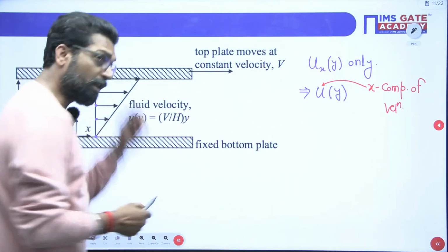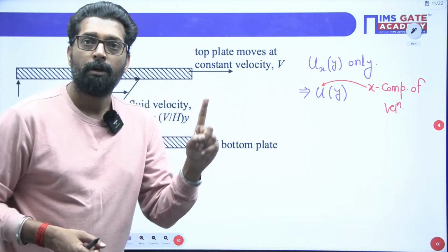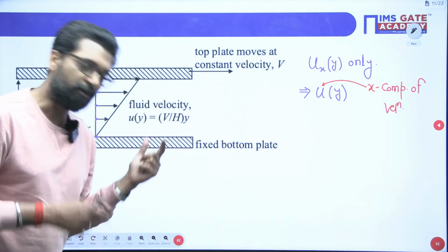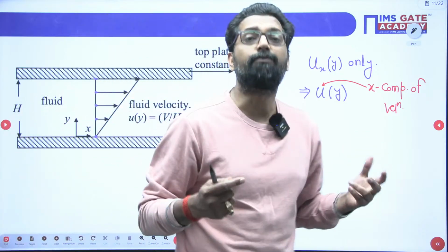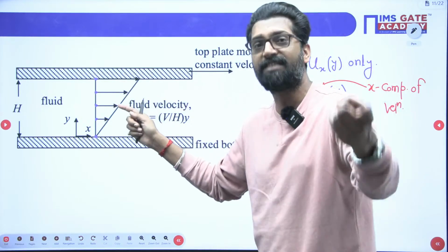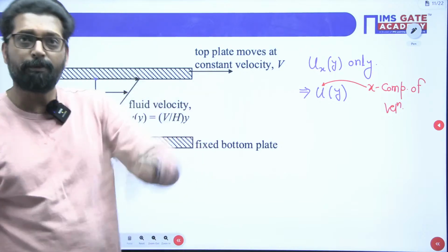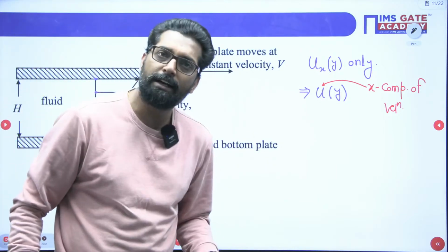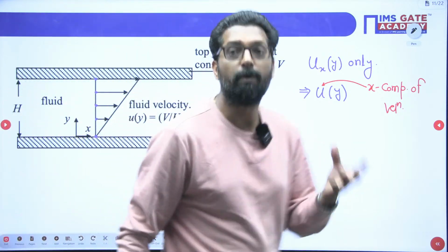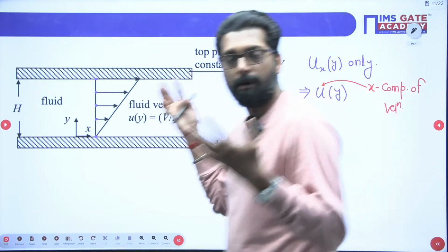Now, what is the profile then? Why do we bother about that? Because we have to find the shear stress within the plate. From the shear stress, you can easily find the viscous stress. Due to that viscous stress, we have to find the viscous force. Once you find the viscous force, you can easily calculate the power lost due to viscosity. What is the power loss when the viscous fluid is present? So you have to design this model.